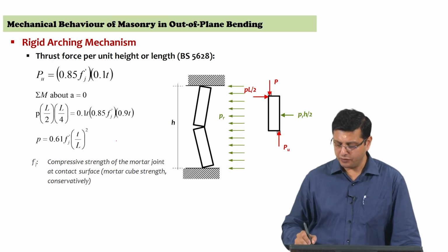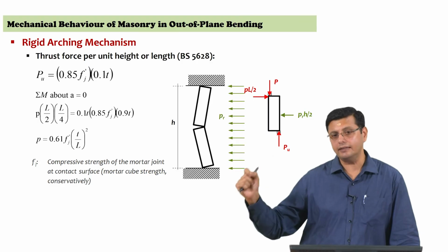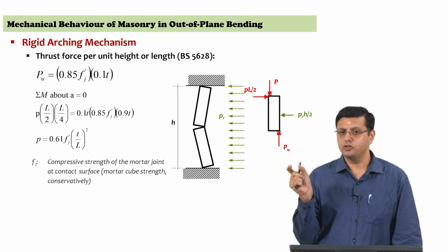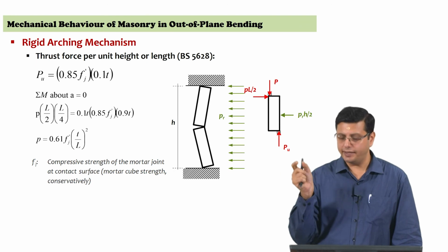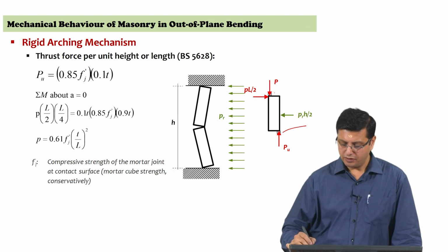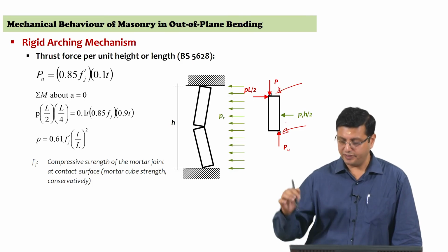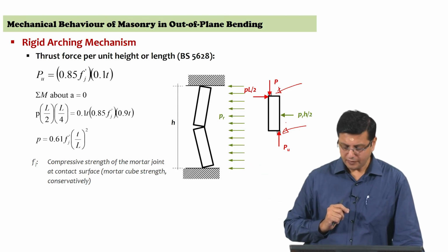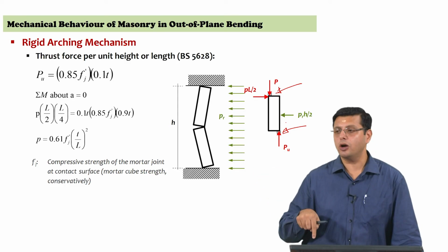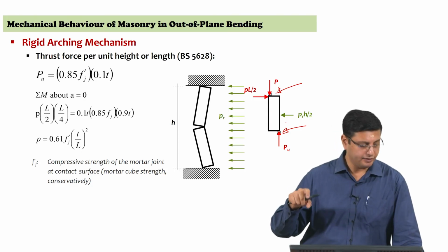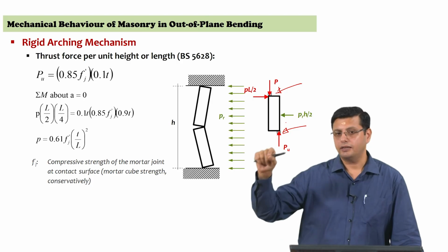So, now instead of assuming that the hinge is forming at a point, we are assuming a finite length, over which there is plastification of the material. So, the same expression that we saw earlier, but now that is not a perfect hinge, but over a finite length. And so, if you examine the stress block in that location, you basically bring in stress block parameters in the compression in the mortar at ultimate.